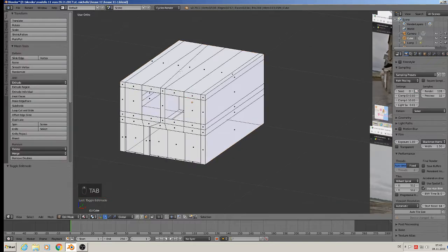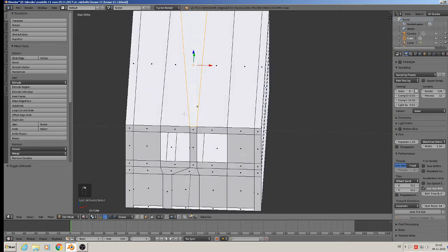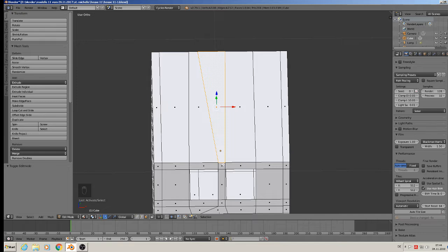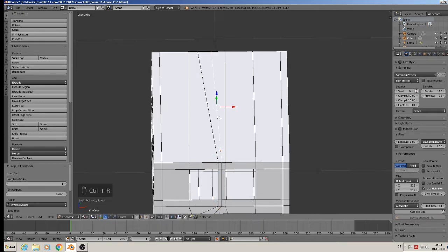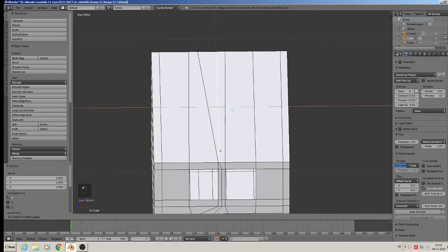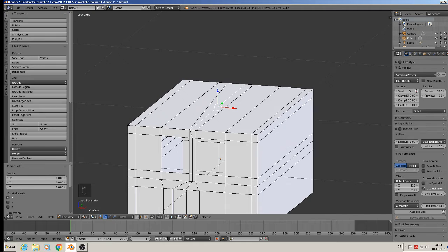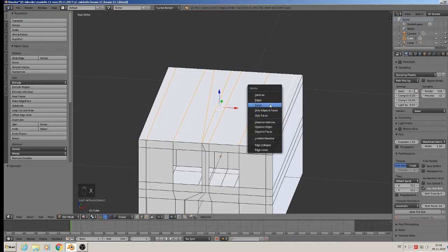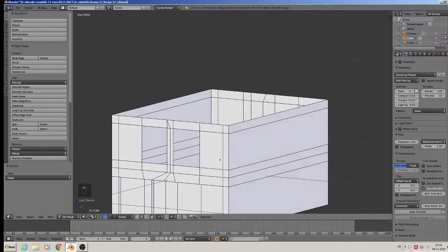There's nothing special on it, so we can take one of these guys here. Best is we make another one in the middle, and that one we say scale X 0. So we have completely the middle. The problem is now when we get them up, then we only get them up. Because of that, we have to do it completely new. So that means we can take all this stuff and X, delete edges. So we have now an open space there.